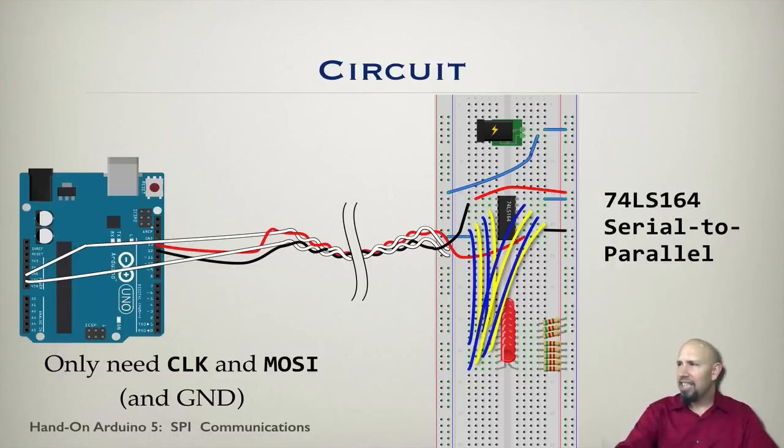So in a sense, these outputs are active low. Okay, so if I want to turn on one of the LEDs, I need to pull the particular channel low. That's important in understanding what needs to happen when we do the code.